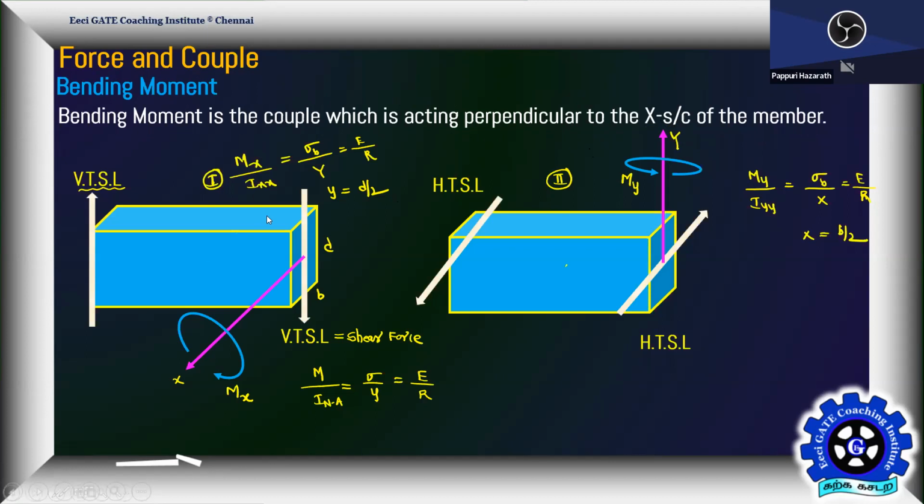Here, what are the different loads? Then immediately they will ask. Two equal in magnitude and unlike vertical transverse shear loads will create a bending moment, or else two equal in magnitude and unlike horizontal transverse shear loads will create a bending moment. In what manner they are creating, you can show. And then what are the bending moment equations we need to use to calculate bending stresses? That part we can discuss later in the strength of material course.